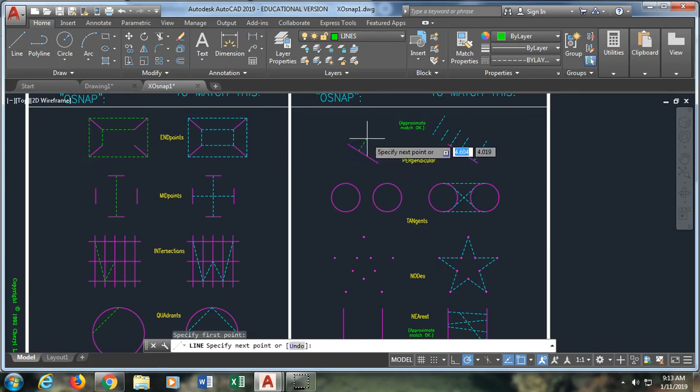And when I start it, it's only going to allow me to drag it out at 90-degree angles, wherever along that line I want to. So you either need to know exactly how far in you're going and have typed in that specific point, or you need to have a guideline of some kind, like a construction line, available. So then you'll go in and just draw your lines.